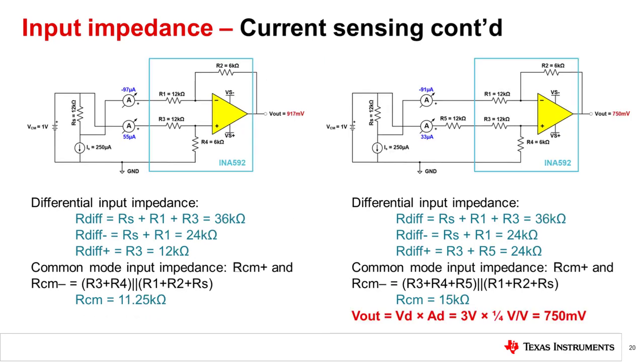You might be asking yourself, what if the resistors are integrated to the IC and you can't switch them out? In this instance, we can add one resistor to the circuit. Let us cover an example of this. Take this INA592, TI's high-precision, low-power e-trim difference amplifier. The INA592 features an integrated precision resistor network to achieve gains of 2 or 1/2, depending on how you connect the circuit. The connection shown here is for a gain of 1/2.